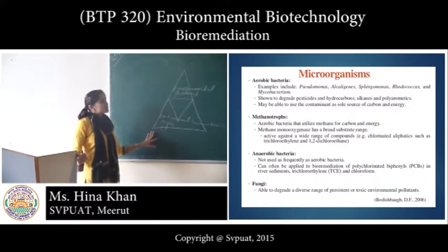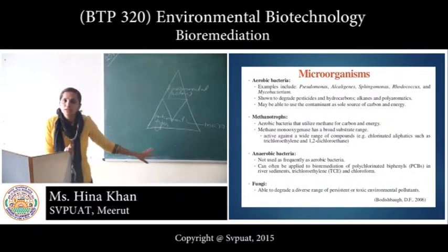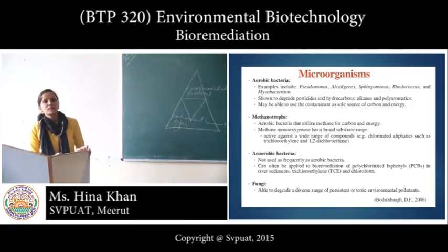So I told you about different types of contaminants present in soil or water. They may be biodegradable, like petroleum products, gas, diesel, fuel oils, and crude oil components like benzene, toluene, xylene and naphthalene, and some pesticides are also characterized as biodegradable. Second one is partially degradable or persistent, like TCE, trichloroethene, a threat to groundwater, and PCE, perchloroethene, which is used as a dry cleaning solvent. And last one is non-degradable, like uranium, mercury or DDT.